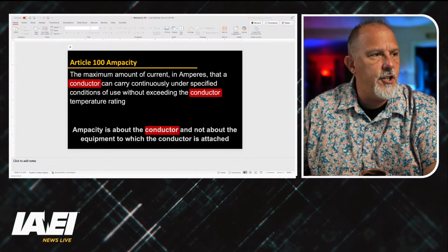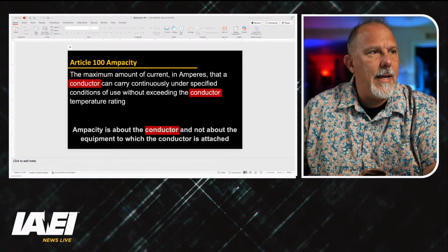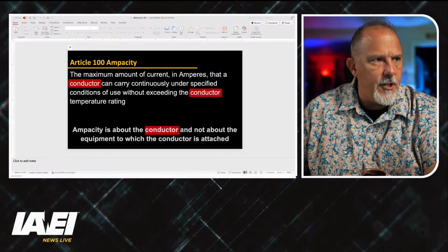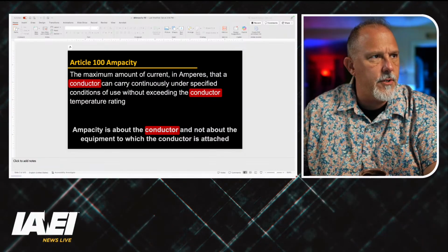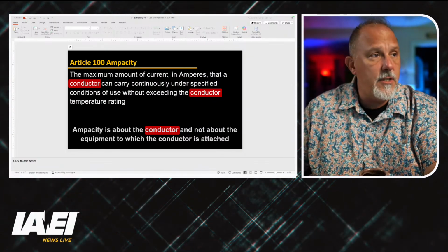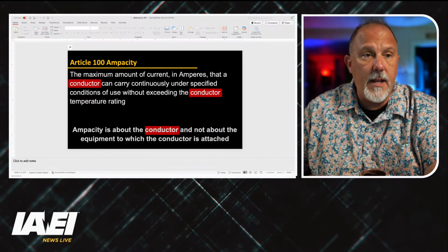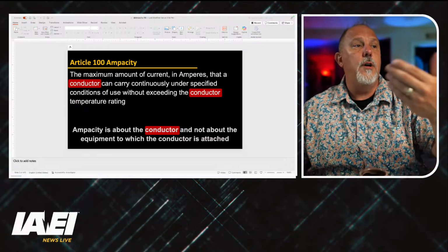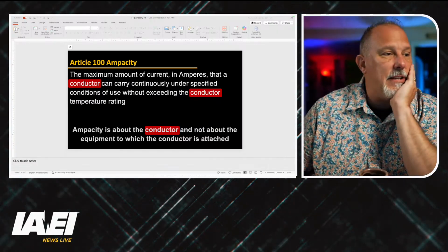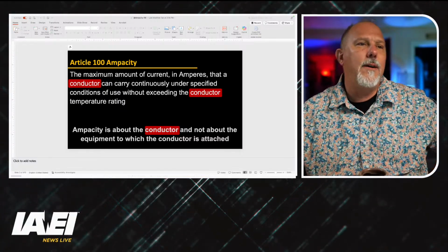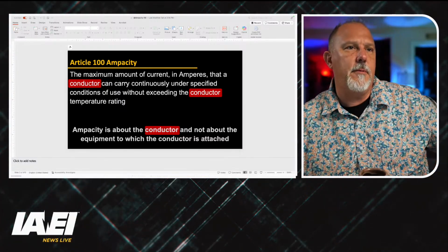I have an engineering supervision, but where do I get into the ambient correction factors? I guess that's just in the general ampacity of the conductor. 310.15 is where I'm going to, I would have expected in 310.14 for it to tell, oh, it does right there. Well, it's the tables as provided in 310.15.